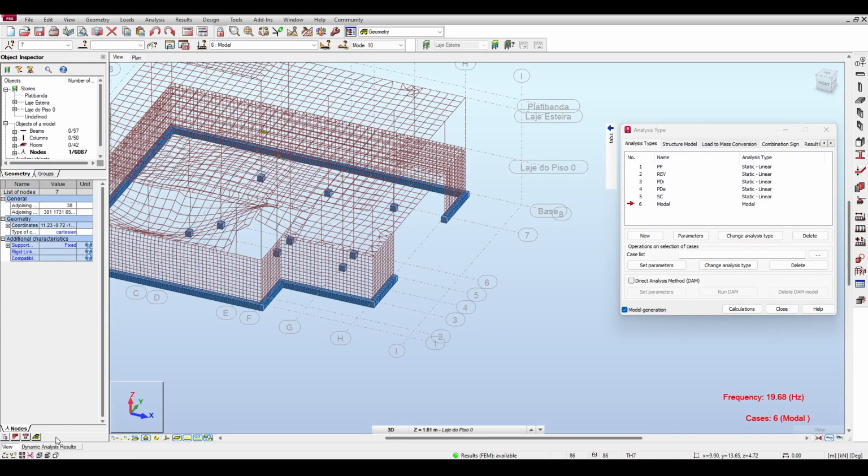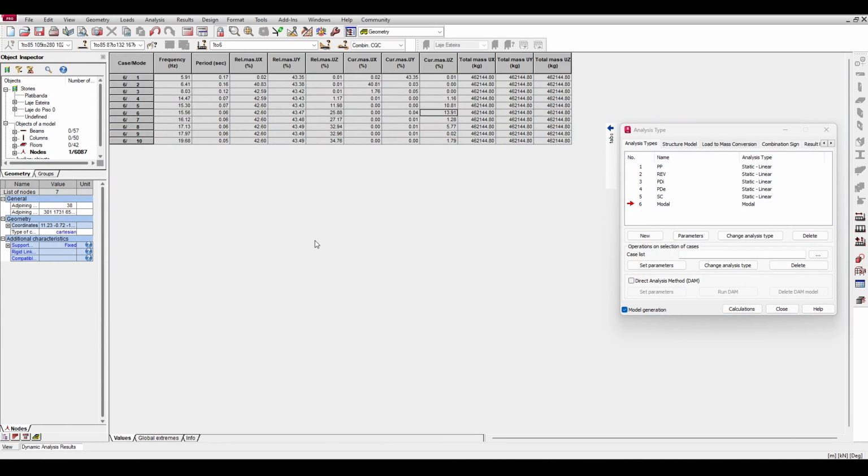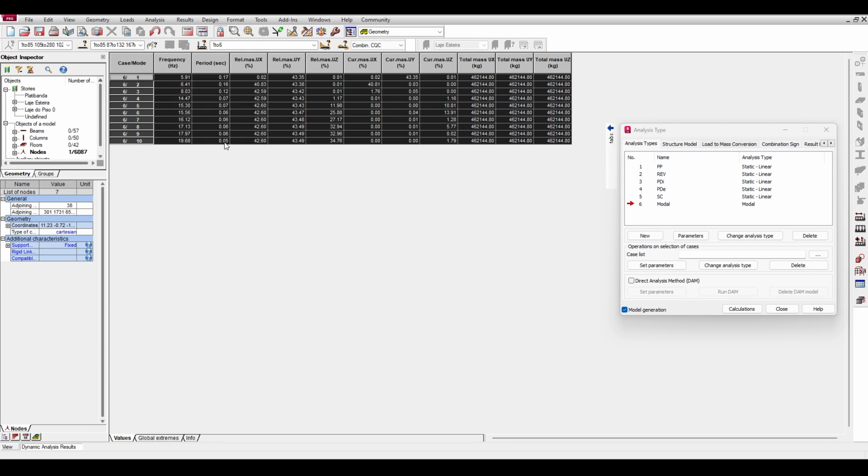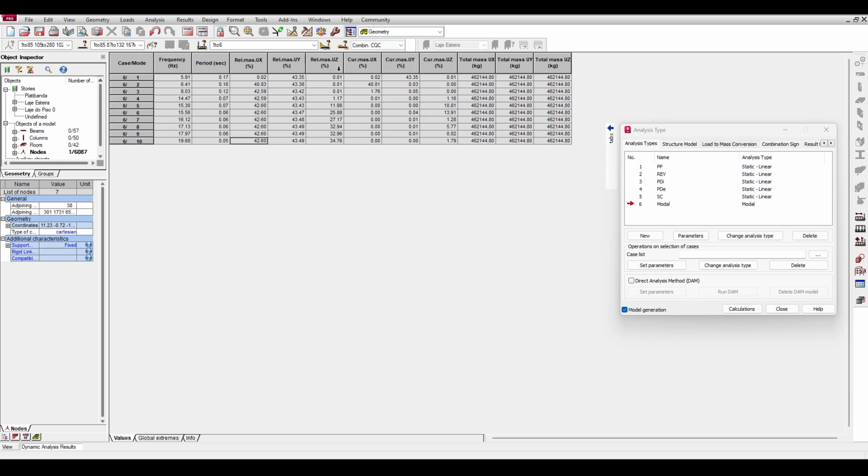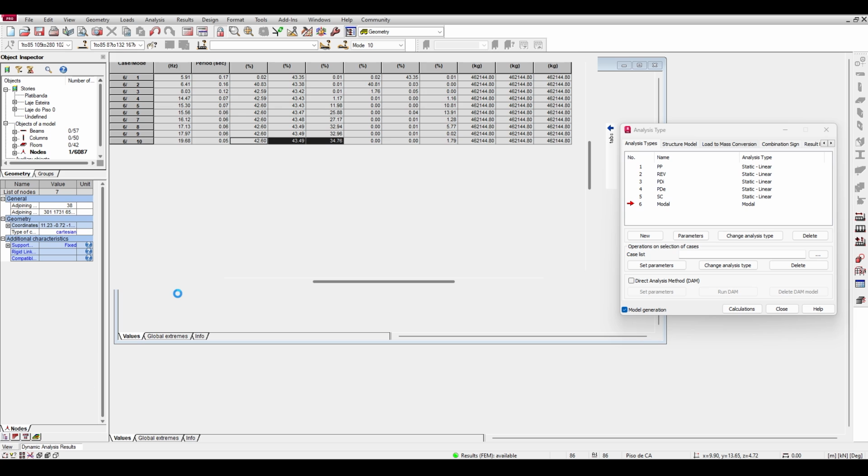Now here's the kicker. The problem with this modal analysis, and that's the reason why Jorge sent me this, is because the mass participation is too low. Allow me to explain this. The problem with the analysis is that the entire mass is not moving. He has done 10 modes and he was only able to get cumulatively less than 50% of the mass to move. Now, why is that? We need to understand, first of all, why this is and what we can do about it.